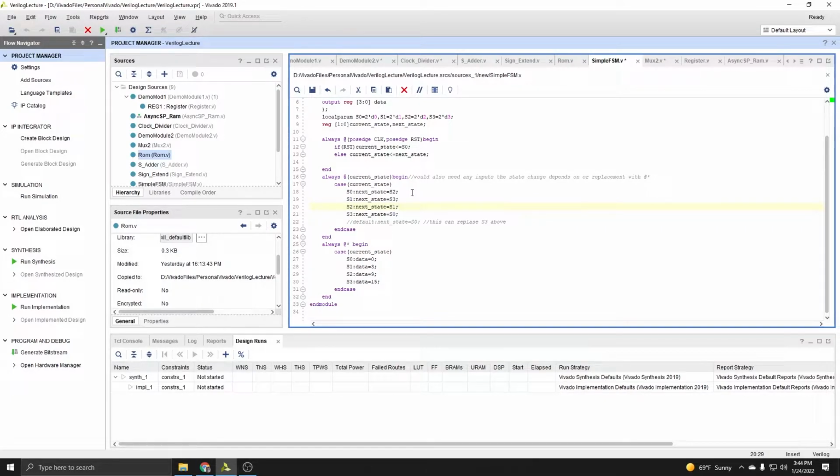But next, I'm going to start going into the tools that you have at your disposal for writing Verilog, one of which is the case statement. This allows for making large decisions where there are several possible outcomes, and making it so that you can write it in an efficient way. Let's say you have 10 possible outcomes to a decision. Rather than having 10 if statements, you can do a case statement, which is covered in the book, but this is the format for a case statement.